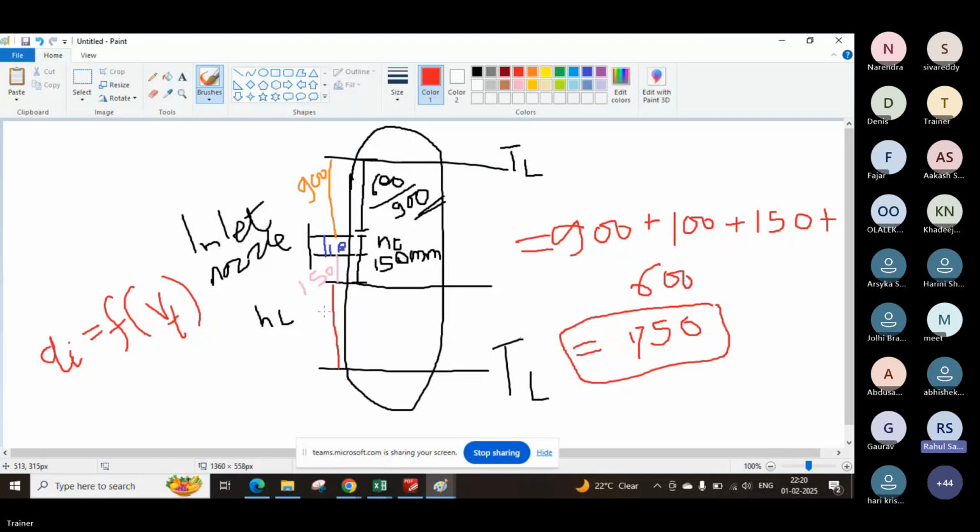Actually, in the vertical separator, as we have considered regarding the height, the diameter will come from the terminal velocity concept. And the height, as we consider, is based on the safety factors and operators' reaction time that we consider while considering the alarms and the trips. In most cases, please correct me if I'm not wrong.